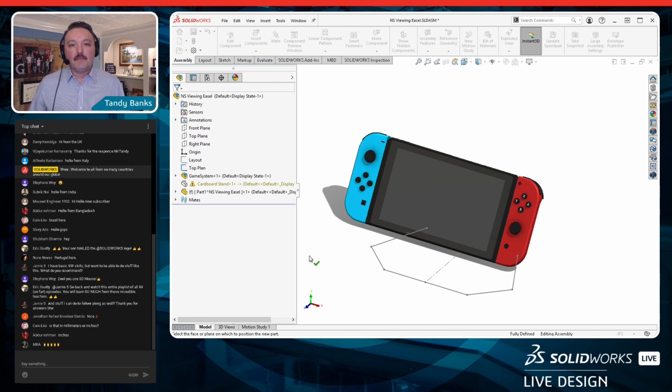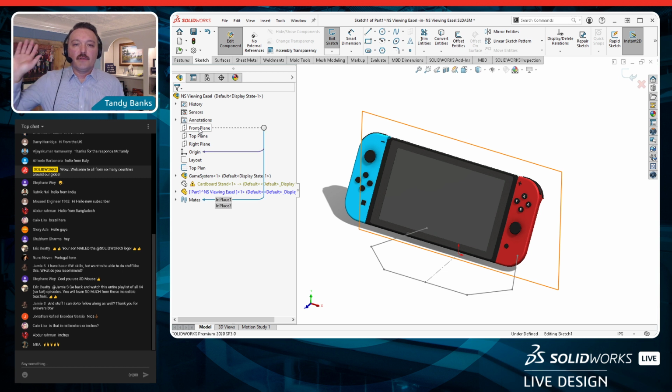And I like my planes and axes and my coordinate systems to match up. And so I'm going to select the front plane up here in the feature manager area. That way it's going to put the front plane of my component right on the front plane of my assembly, and they're going to match. Right and right's going to match, top and top's going to match, and so it puts me there. It also automatically kicks me into a sketch on that front plane.